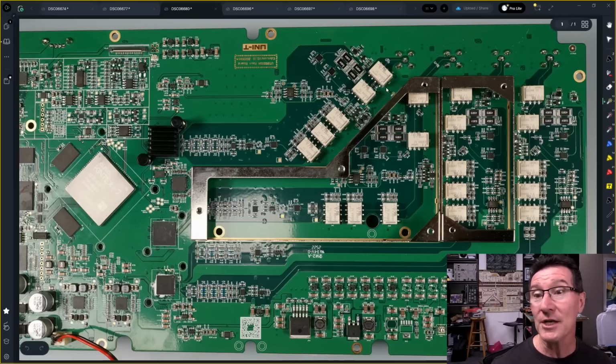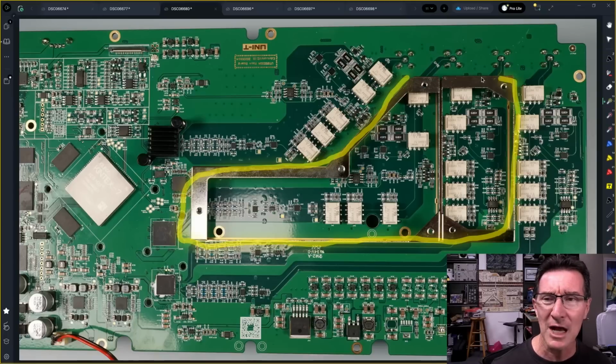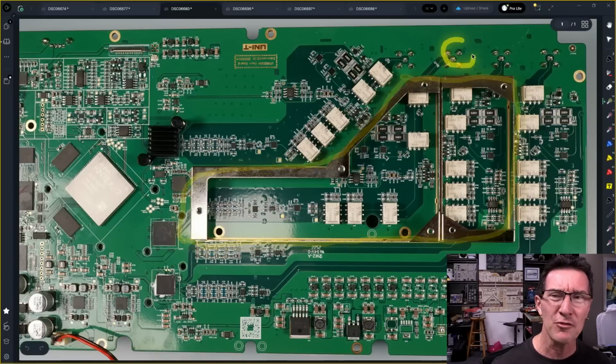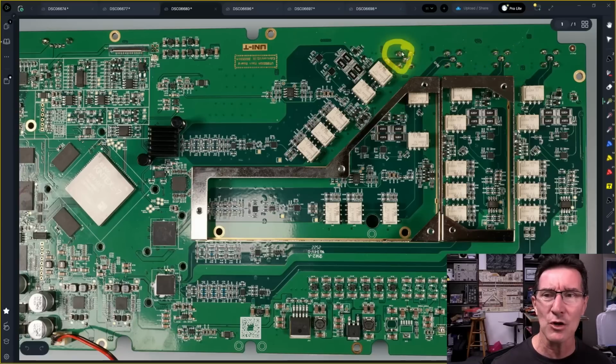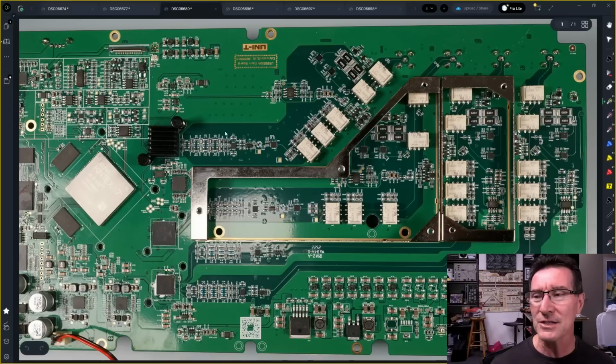Just as a little aside, you might be asking, why is there only shielding on 2 of the channels, channel 2 and channel 3? What's so special about them? Why don't channel 1 and channel 4 get shielding? Well, in this particular case, it's a nice cost-cutting measure because Uni-T, the designers, decided that, well, this is all low impedance stuff, right? DACs are really low impedance outputs. We've got, you know, like 50 ohm drive, really low impedance driving out of here.